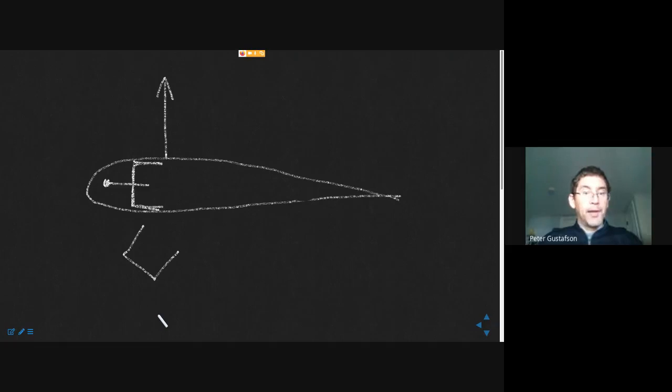Now that actually might be good, right? We actively want the wing, as you increase the load, let's say you get a gust, if you design it this way, then the twisting that occurs actually decreases the angle of attack and somehow mitigates the gust.